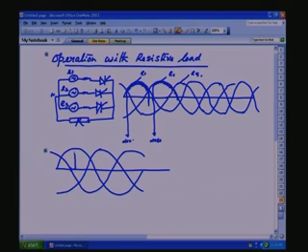So, the envelope will be like this. At this point the commutation stops, the thyristor switches off, but the next thyristor will be turned on only here. So, the voltage ripple coming across the load is different from that of an inductive load. So, this is the portion.